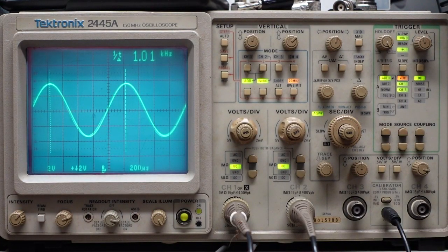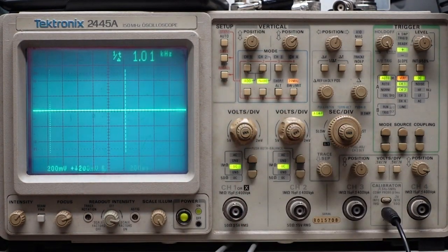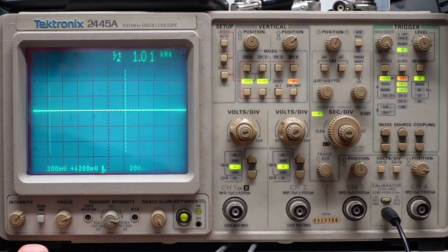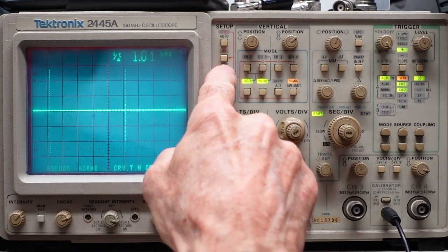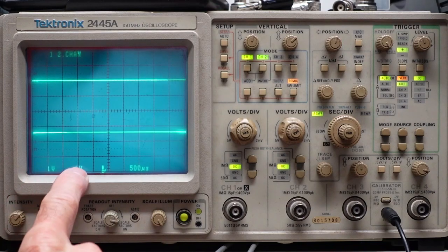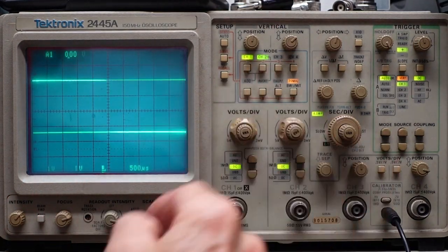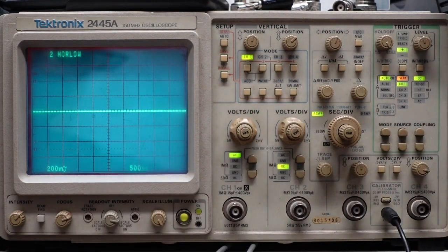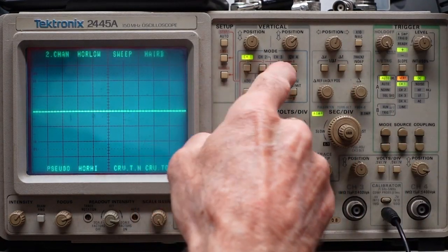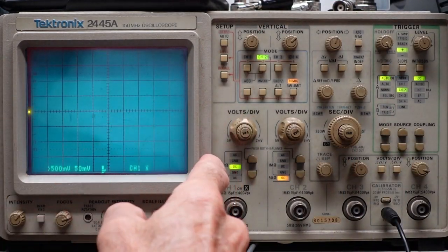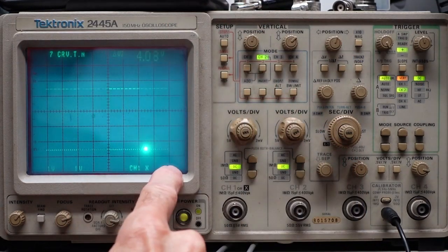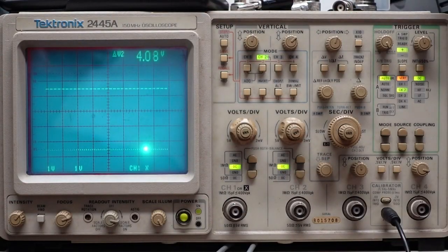The other thing that this scope does that I absolutely love is it has presets. Now, I commonly look at both channels from the output of my distortion analyzer, and I have set it up so that I can just hit recall, set up both channels, 1 volts per division, DC coupled. Preset number 2 is channel 1 only, AC coupled. That's for taking a probe and probing around. Then I have some XY functions like this. That's for using a sweep. I have some XY functions for using my curve tracer, but it's a shortcut.